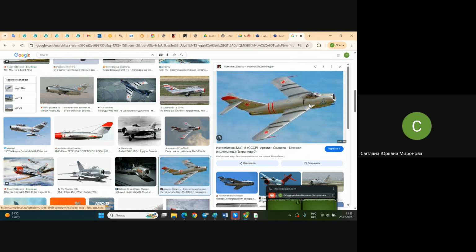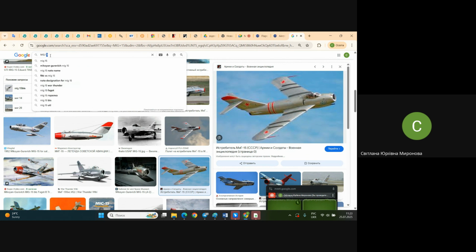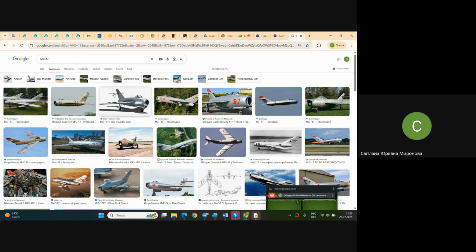No, we do not have a MiG-15, we have a MiG-17 right outside the windows of my office in Hawaii. But you see, they are not much different. They both have fences, and these fences are necessary to prevent motion of air from the root to the tip, like downwashing along the wing, which may happen in case you have a swept wing.